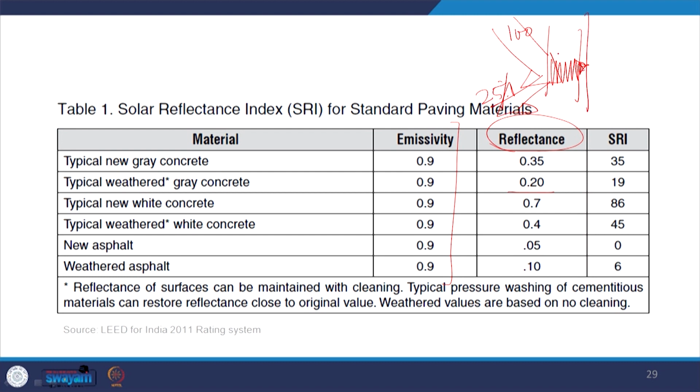Now, of this which is absorbed, not all will be transmitted inside. During night time, when the outside temperature falls, the heat which is absorbed will be re-radiated to the outside. When the temperature of this surface is higher than the atmospheric temperature, a part of this heat will be released outside, and if the indoor temperature is the same as the outdoor one, it will also release equally to the inside. This depends upon the temperature difference between the surface and the outdoor air.